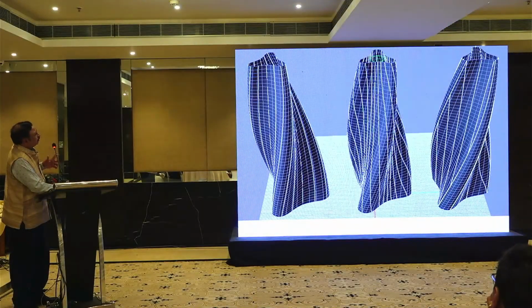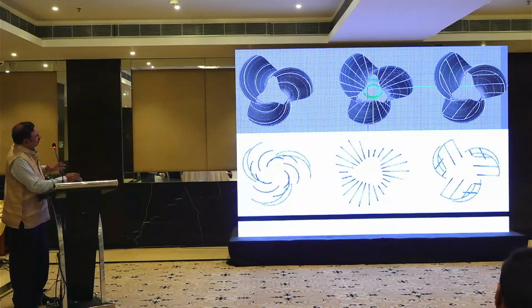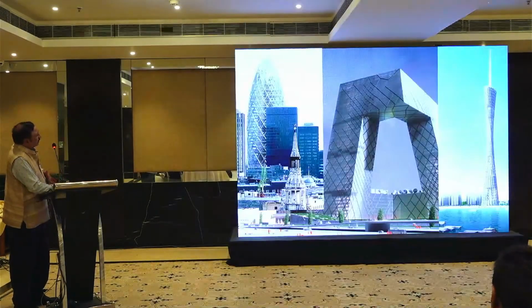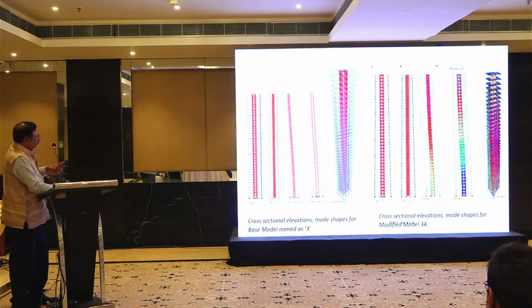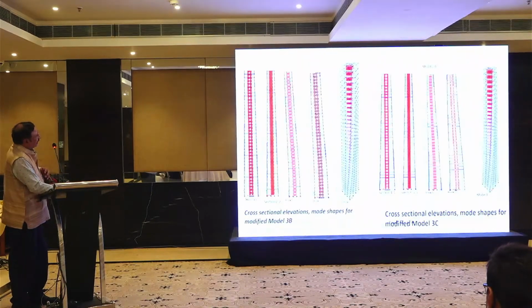So everything has to be done. You just cannot do gravity analysis. You have to study the mode shapes, arrive at the configuration, and only then decide this is good. Then you can come out with interesting ideas. Again, this is somewhere in Dubai where I had the opportunity to visit. And these are all the results of his studies, which he has made with different ETABS models.